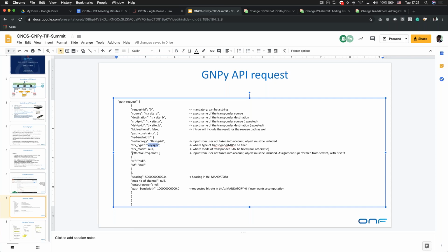So this, I don't particularly know exactly what this slot is. So Jan, do you have any ideas of what this is? Yes, I'd appreciate it. So this refers to the ITU definition of flex grid, which unfortunately does not work directly with a range of frequencies or a center frequency and a channel width, as in gigahertz or megahertz.